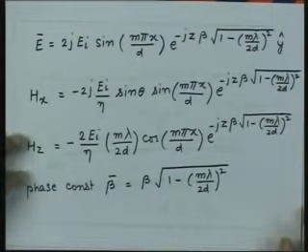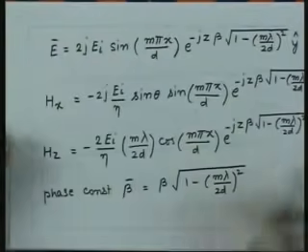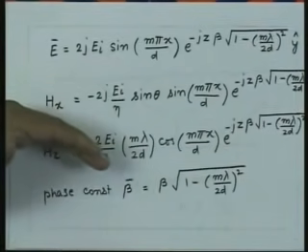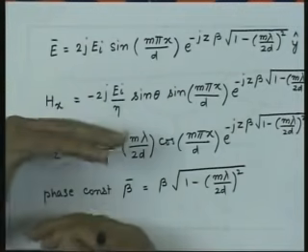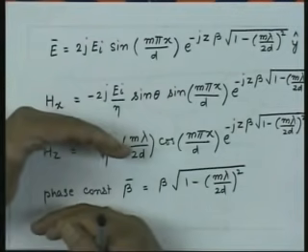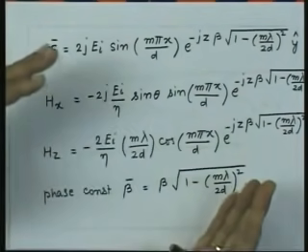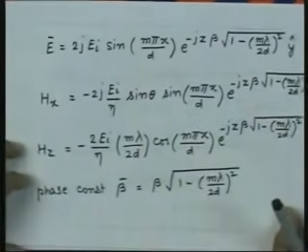So, what we see from this analysis is that when we have a bound structure like a parallel plane waveguide, firstly there are discrete angles at which the uniform plane waves can be launched inside this. Superposition of these uniform plane waves which are bouncing back and forth between two parallel planes gives you the field distribution which will be like this, and those field patterns we call the modal patterns.